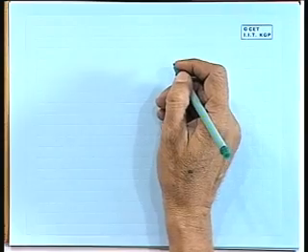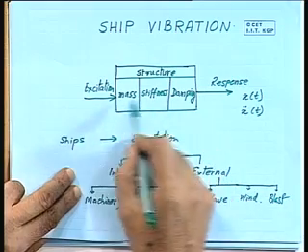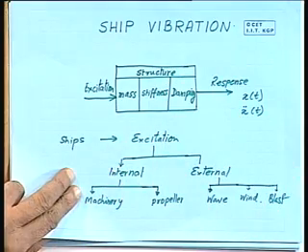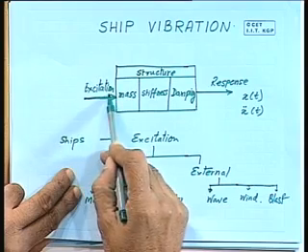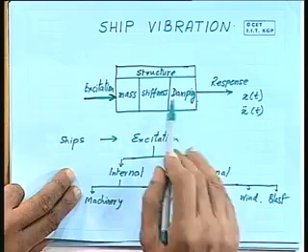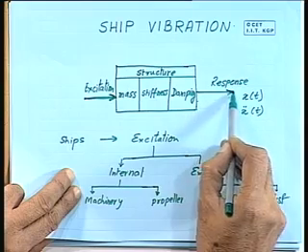Now, once again when we go back to this diagram, we take a structure which is represented by one single point, and the displacement will be only one single displacement. That is how we are going to get 1 degree of freedom. So, there will be some excitation to this one single point or single mass structure, and we get one single response here. Okay.